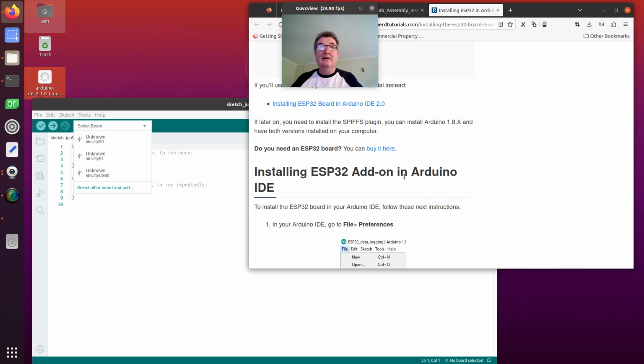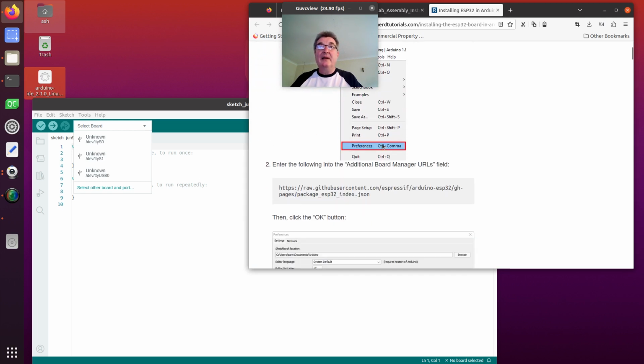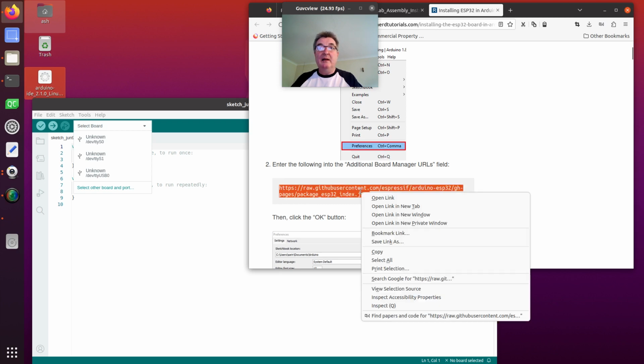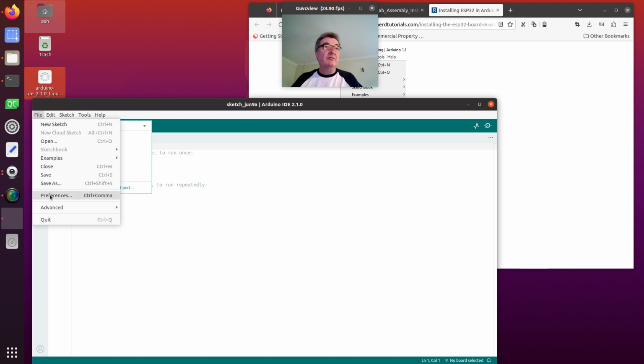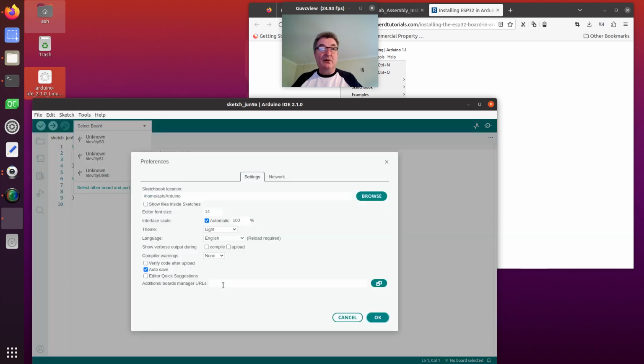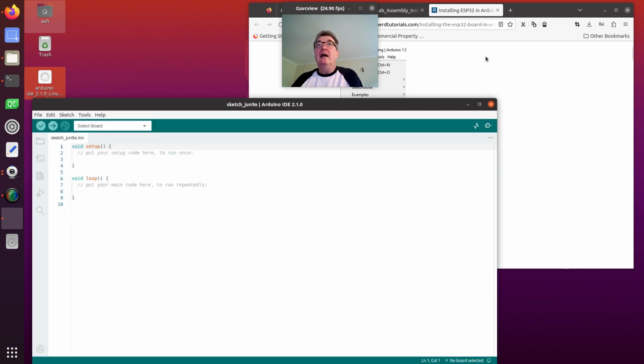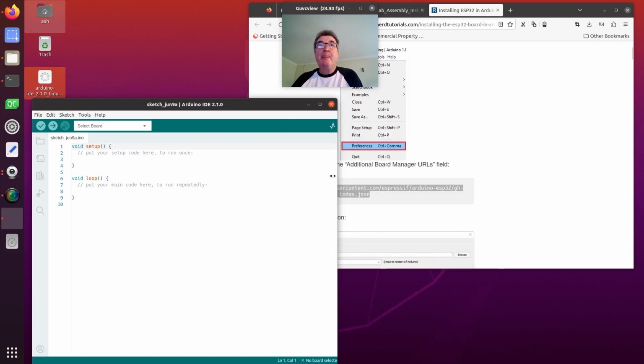There's file preferences, yeah. So we need to copy and paste this. So under file preferences, additional board managers. So we put that in there and just click OK. Once you've got that done,